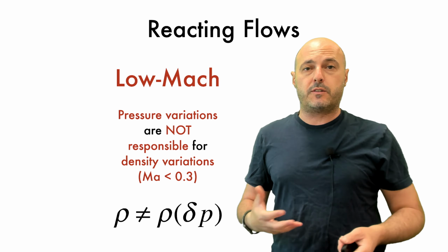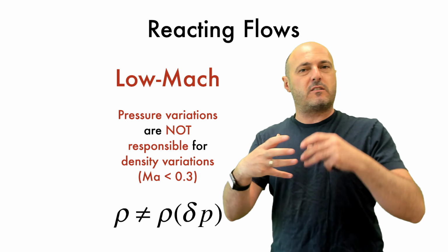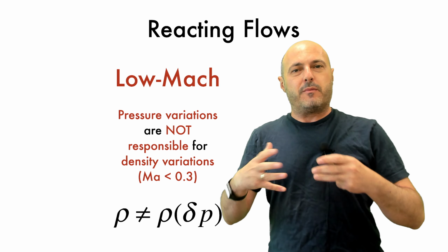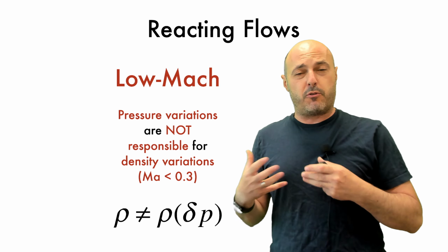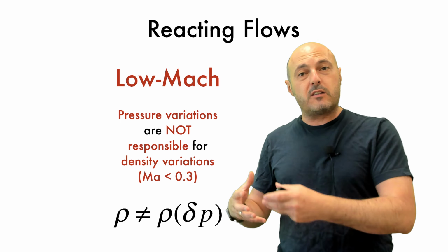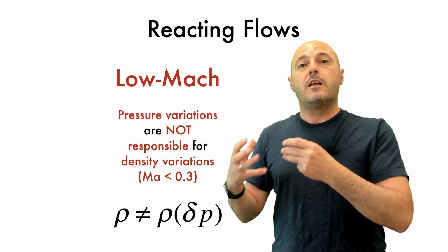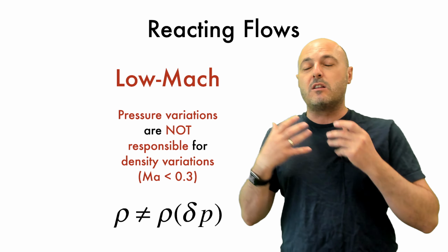Now, specifically for low Mach flows, the observation is first made that pressure variations do not cause significant density variations. So take a candle, for example, or a flame, and go sing for it or play music for it. It doesn't change the reaction, it doesn't change the density changes that are happening due to the reactions. Rather, it is the heat release and the reactions themselves that are causing the density changes, not the pressure. Okay.